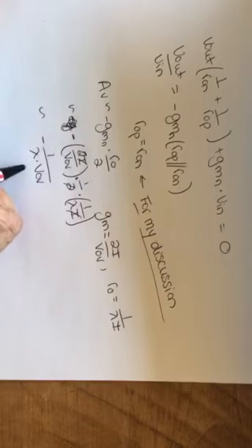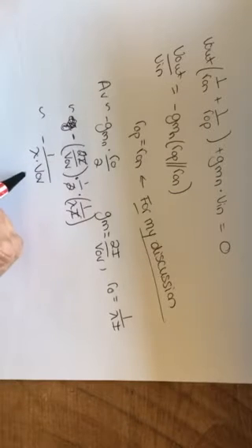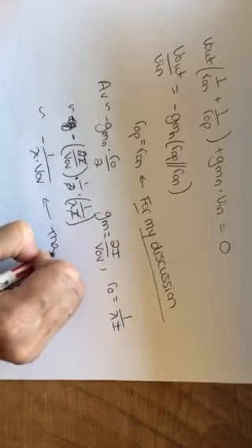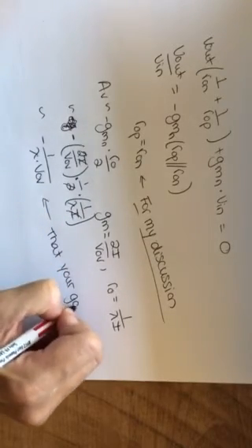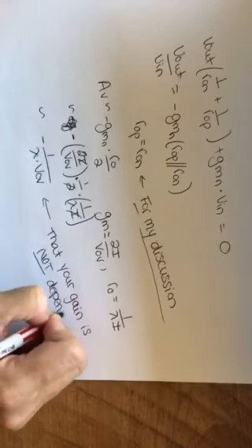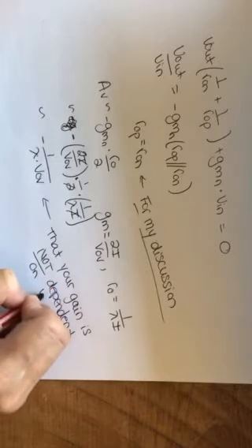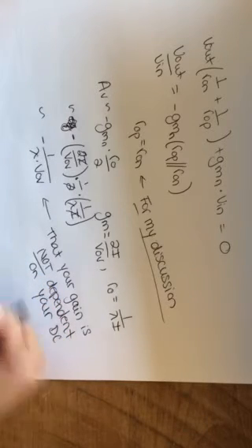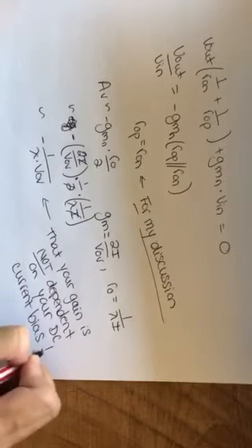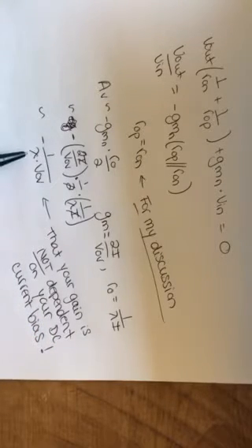So if you look at this voltage gain, you see that the current has been taken out of the equation. It is not dependent on your DC bias current, okay? So this is showing that your gain is not dependent on your DC current bias, right? What does it depend on? Well, it depends on the lambda, which is a process parameter, and it depends on your VOV.